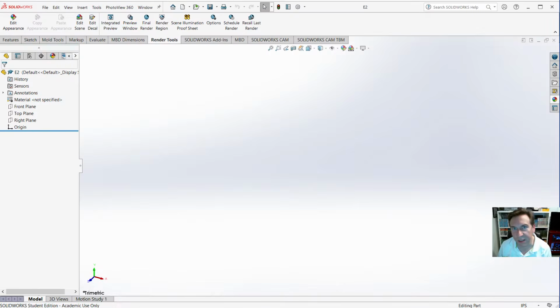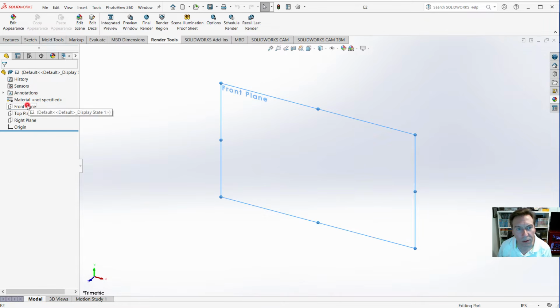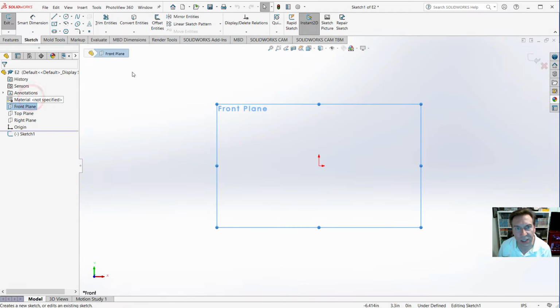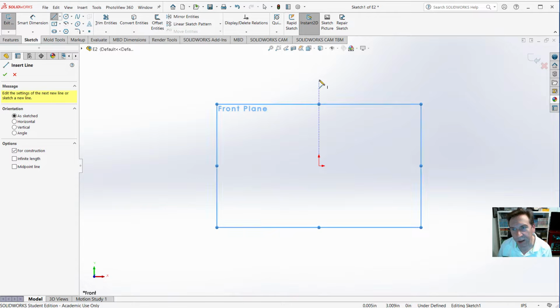So let's go select the front plane, start a sketch, go to the little arrow to the right of line. And now if you did Lab 1B, we used the Centerline Tool. I showed that to you briefly. So this is a review for those of you who have done that. If you haven't done the lab yet, it's new to you today. So go to Centerline. Now hover just directly above the origin. You'll get the line of inference.